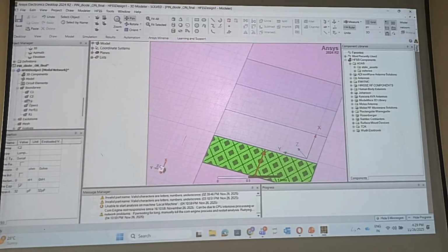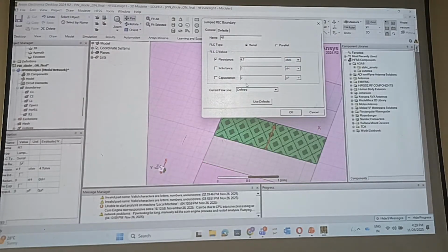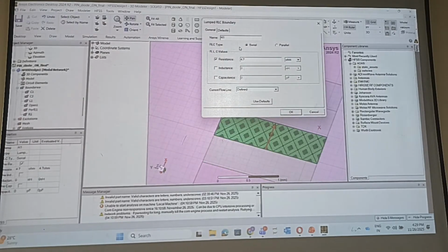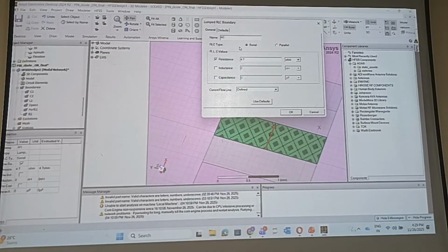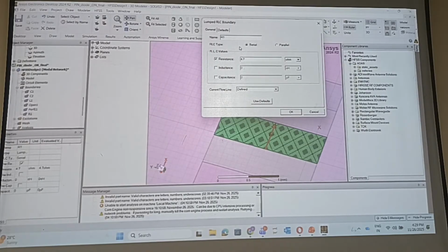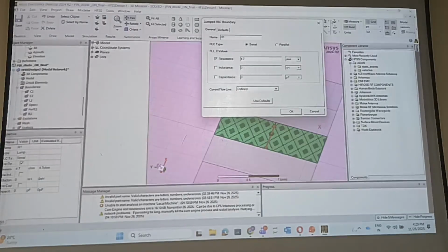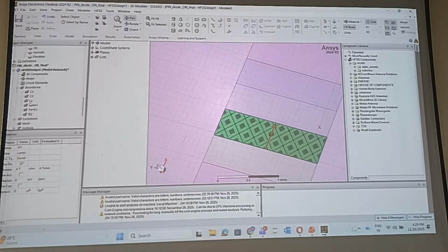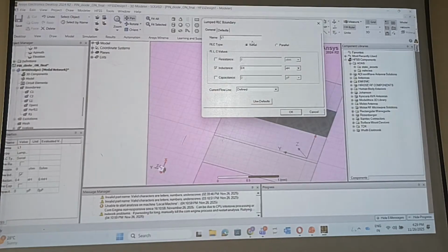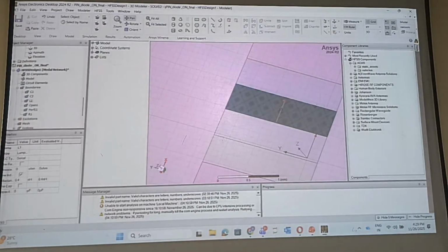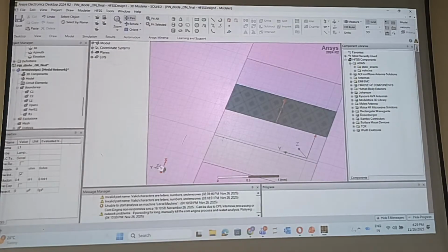click on OK. The next 2 points are resistor. So since it is series connection, resistance value will be in forward bias, resistor will be very less. So I have selected 4.7 ohm only, since it is in forward bias. Now, in case of inductance, same way, inductance value is 0.4 nanohenry, and again the connection is series. Now let's see for the off condition.